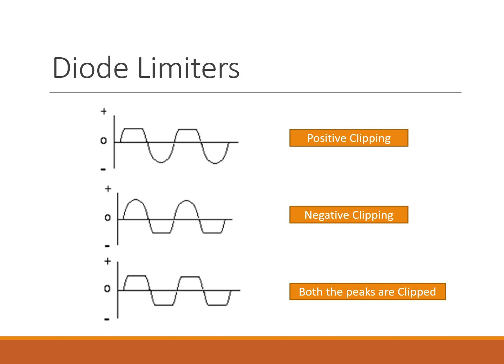Now, the third image, the dual clipping, where we clip both the top and the bottom. We have two diodes in this case, one forward, one reverse. One clips the positive, the other clips the negative, and in the output only the middle portion of the waveform passes. Both top and bottom are chopped, leaving a nice little clean window. You can use these for signal thresholding, pulse shaping, or amplitude protection circuits. A good design tip is that you can clip to any level, not just 0, by adding a DC reference voltage in series with the diode, and we'll see what that looks like in an actual circuit.